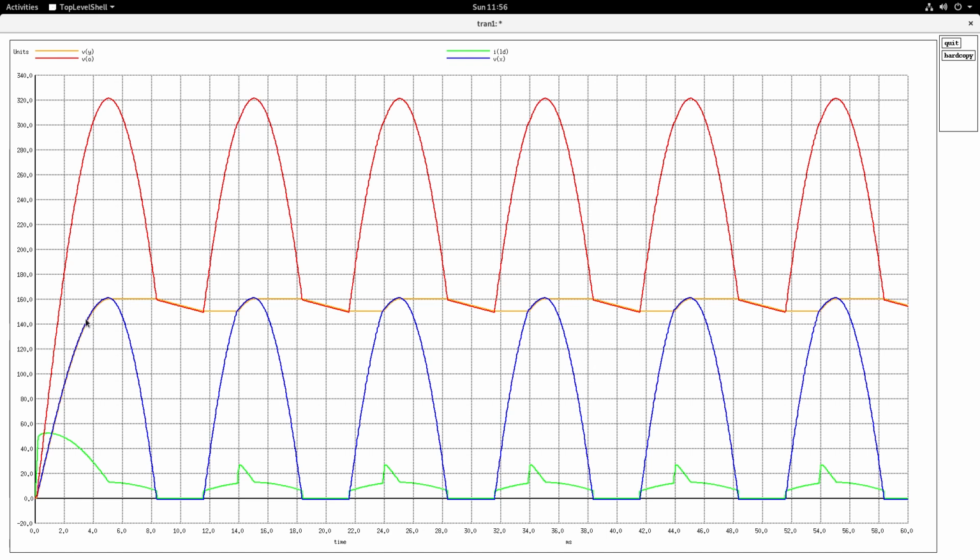After it has followed the input and then come to the 50% mark, Vm/2, it then holds there till the input voltage comes below the Vm/2 point, when the rectifier diodes stop operating and the capacitor is discharging into the load. Each capacitor discharges into the load till again the input comes up and then crosses over here, the rectifier diode comes into operation, and then you have the output following the input.